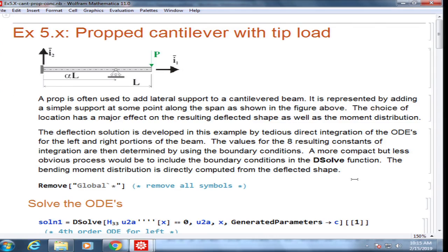This roller prevents the movement along I2, so it doesn't allow any transverse displacement, whereas it allows a longitudinal displacement. Longitudinal displacement is allowed because we don't want any additional stresses for the beam in bending.